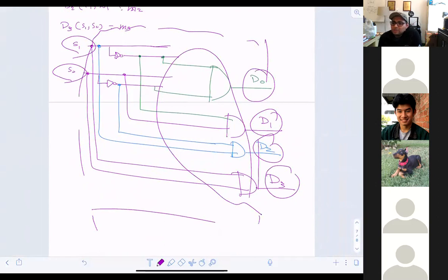Okay, what is the longest path we have now? I have no idea. What is the longest path and what is the weight of it in terms of the response time? The response time is going to be something like this. This is the longest one. Anything involving the NOT gate with AND, a NOT gate followed by an AND gate. Then you will see the timing from the manual, and based on that you will say this decoder will take this amount of time to produce an output. Make sense?